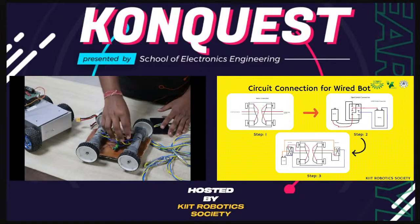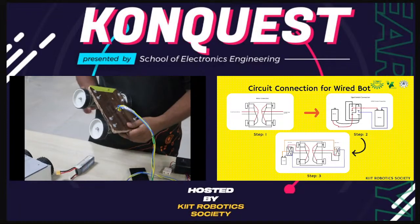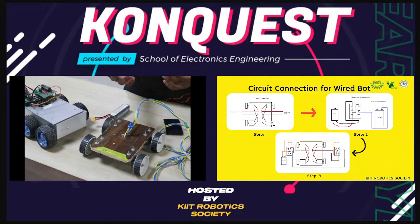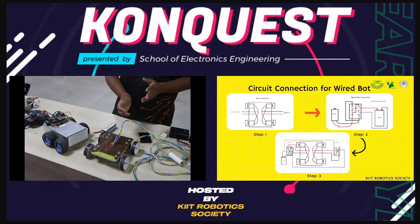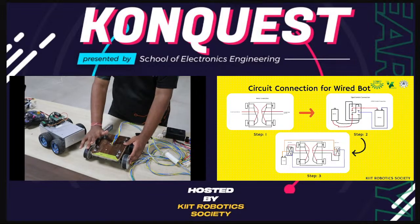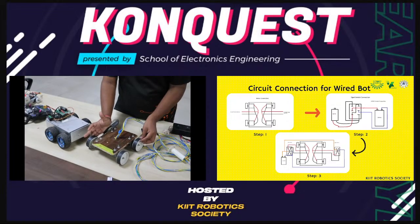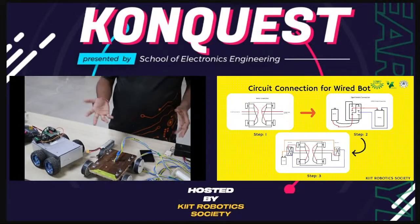In simple terms, this bot will run like this: for the forward direction all motors will move forward, for backward all motors will move backward. For the left turning, it's like a tank: these two motors will move backward and these two motors will move forward. For the right turning, these two motors will move backward and these two will move forward. That's how it's a tank type of bot.